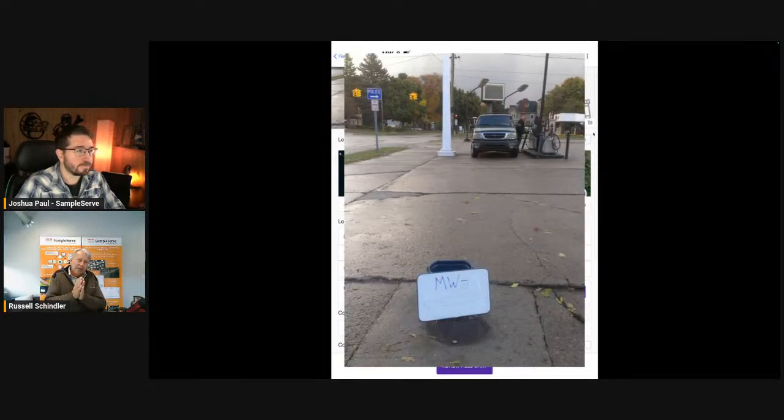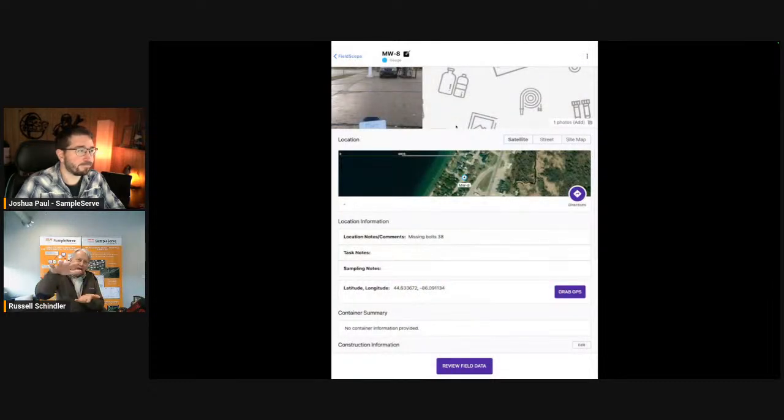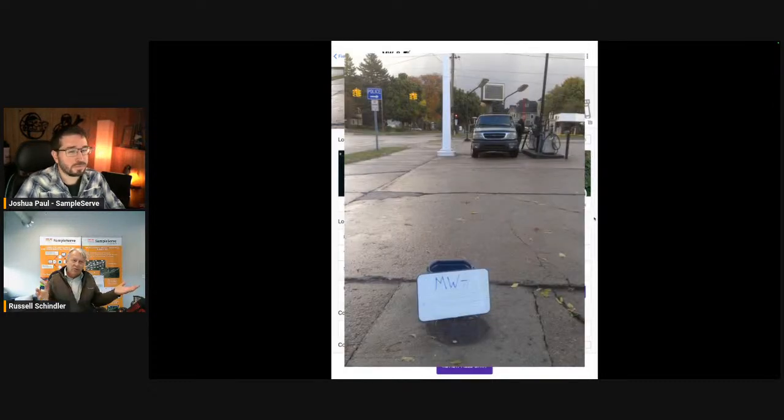And what I typically would do is, so I know this site right here, it's actually way up north, and there would be lots of snow on this site. And so, in the wintertime, there would be a 2-3 inch packed layer of ice on the pavement there. And the concrete was loaded with rebar, so even a metal detector wasn't much help. But I would pull out the photographs, and I would take 2 photographs, one looking this way, and then I'd go 90 degrees to the other direction, take another photograph.